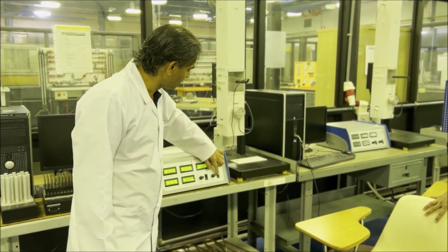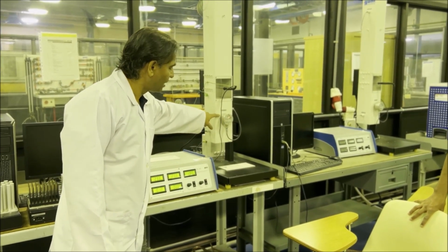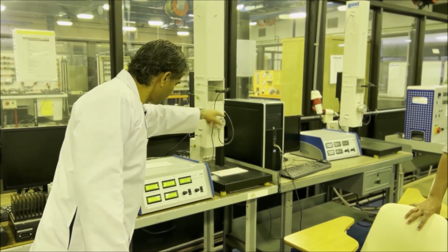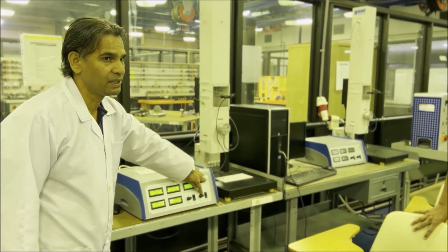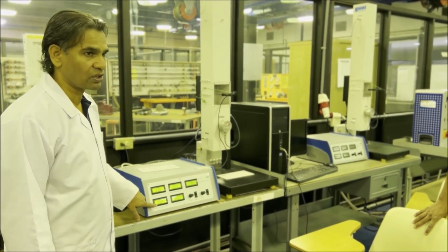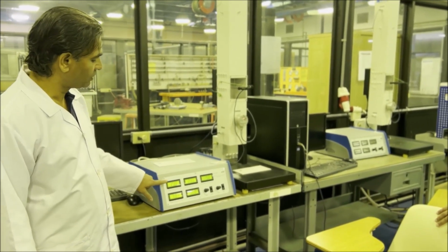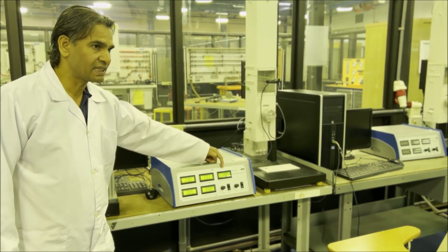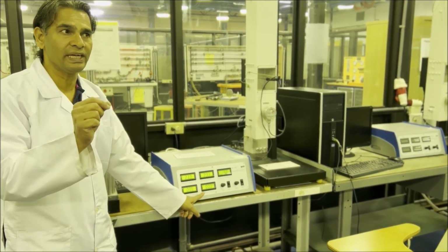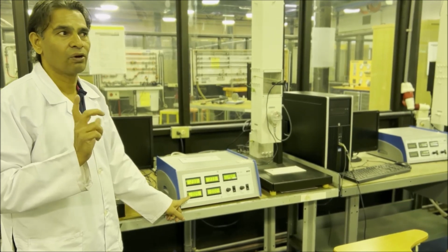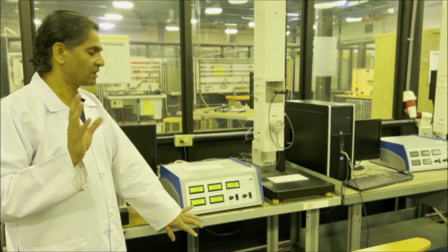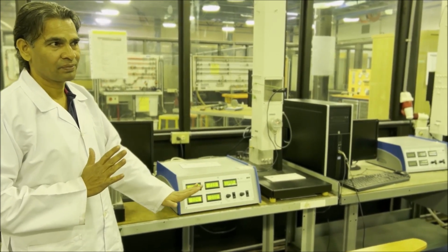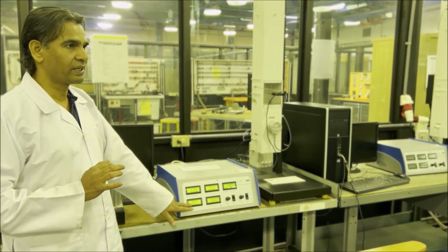This is a fan anemometer where we can measure the velocity, and we can change the velocity from here. This is the fan speed, we can change the speed so that we can measure the velocity here. What we need to measure from here are TA and TH. Then adjust the power to 80 watt and vary the velocity: first reading, second reading, third reading. Whatever is displayed here, record it, because it is not stable.